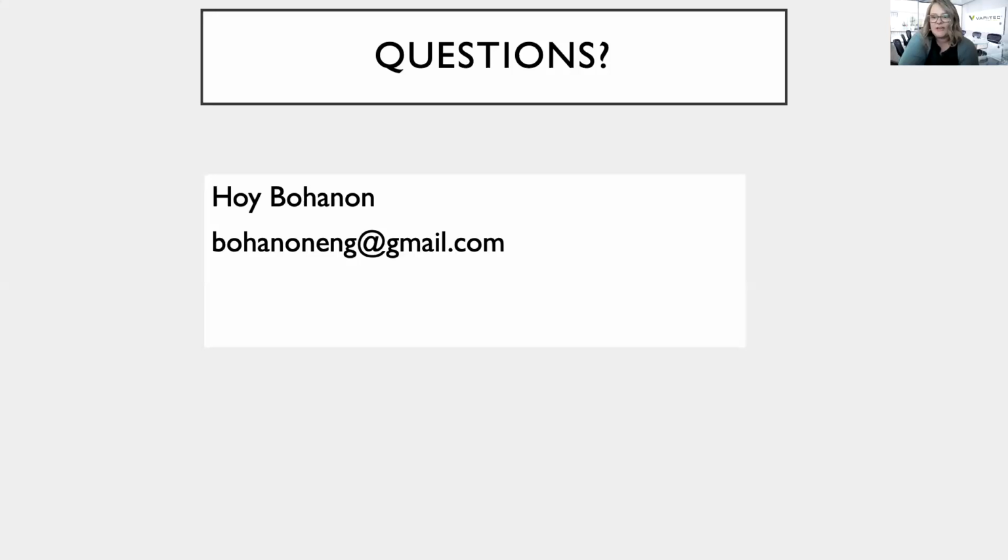Also, with regard to current ASHRAE guidelines on reopening of schools, they recommend 2 additional air changes per hour. This is above the suggested air change rates for the space. What happens if you have no ventilation in the space currently? I would not agree that 2 air changes are correct to effectively ventilate.